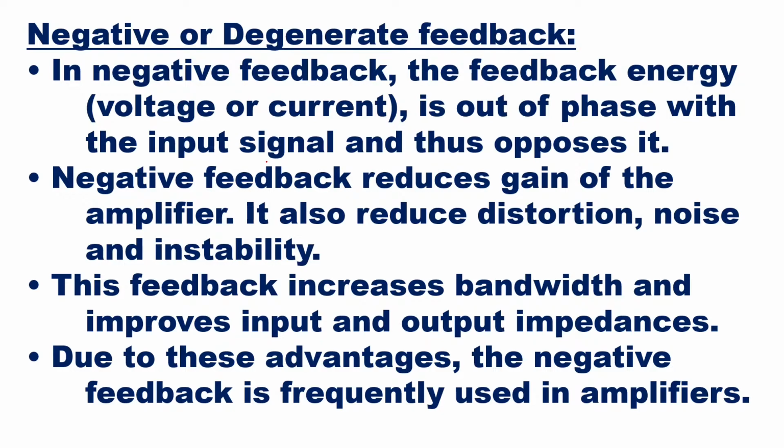It also reduces distortion, noise, and instability. So the circuit will become more stable if you are using negative feedback, and that is good for amplification. This feedback increases bandwidth and improves input and output impedances. Due to these advantages, negative feedback is frequently used in amplifiers. So here we have seen that negative feedback is a feedback which is used for amplifiers.